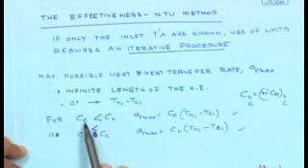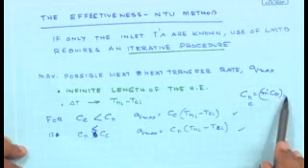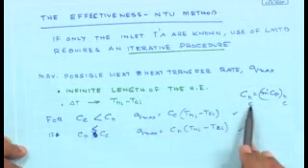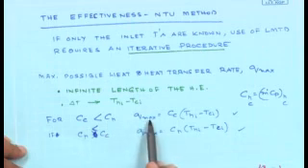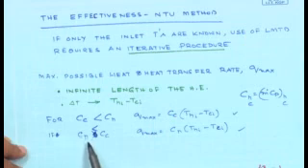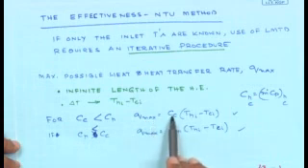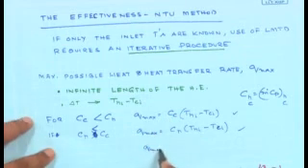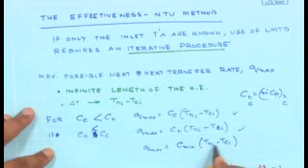However, the capacity is defined as m dot Cp, so Ch, the capacity of the hot fluid, would be m dot Cp corresponding to the hot fluid, and for the cold fluid it's simply going to be m dot times Cpc. So if Cc is less than Ch, then the maximum amount of heat that can get transferred would be Thi minus Tci times Cc. Similarly, whichever is the lower of the capacities between the cold and the hot, Qmax is simply going to be the capacity of the one which is the minimum. So I can write Qmax as equal to C minimum times Thi minus Tci. This is the maximum temperature drop that can take place, so Qmax is related by this.